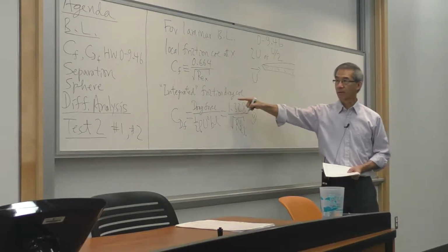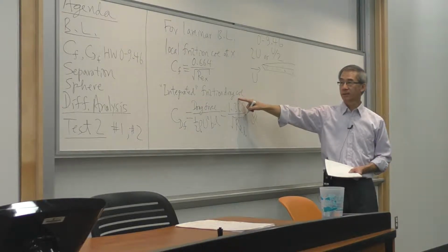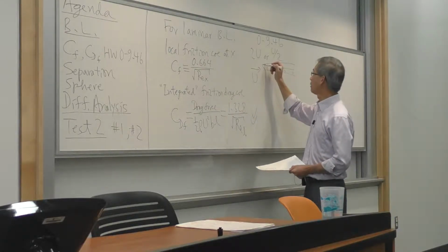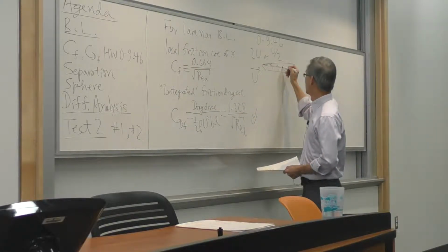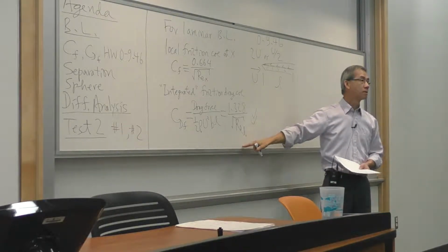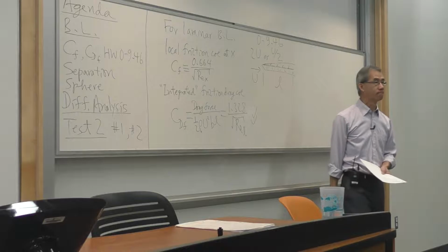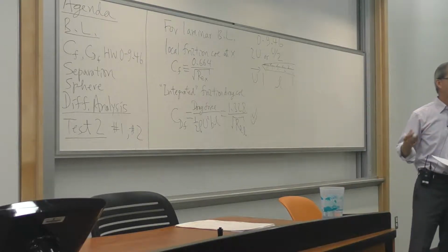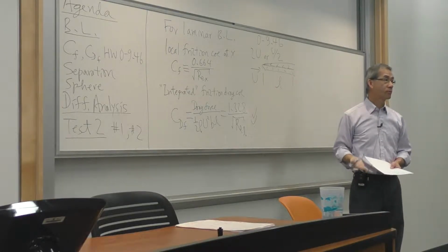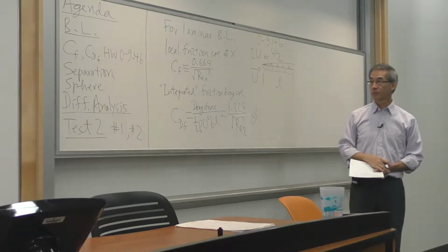So all that boils down to is the use of this equation here, which is what I call integrated friction drag. So the numerator here is the drag force. Integrated, meaning all from the leading edge onto a specific distance of length L from the leading edge. That, in most cases, is all you care about. An overall effect due to shear that worked itself as a friction and created what we call the friction drag, the shear drag, different from the pressure or form drag.